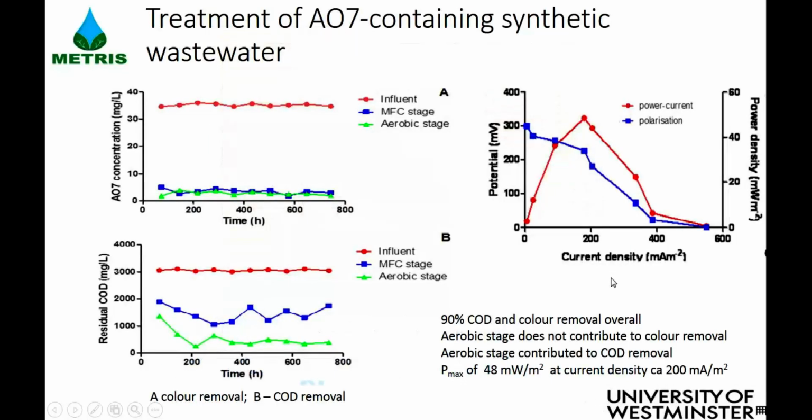With regard to color removal, COD removal and power production for the synthetic wastewater, this slide shows you that you can achieve very high efficiency. So 90% COD removal as well as over 90% color removal overall. What we also see is that the aerobic stage, represented here in green, does not contribute to color removal.